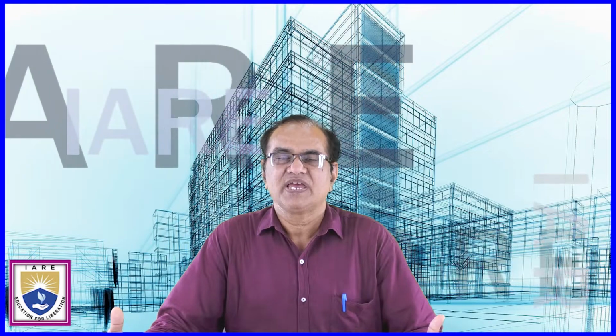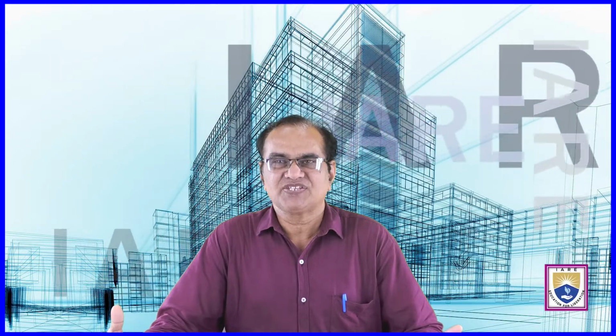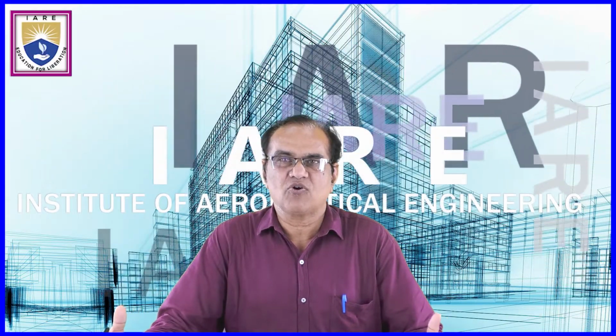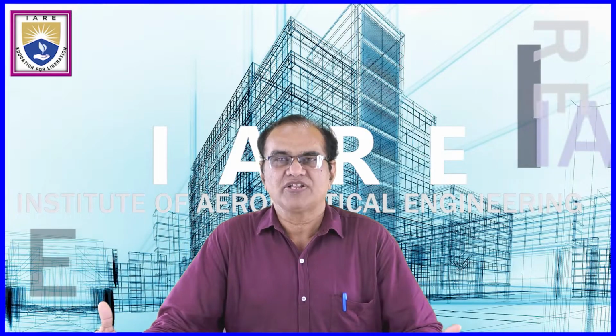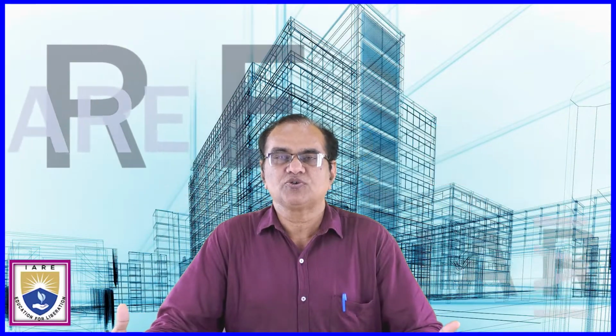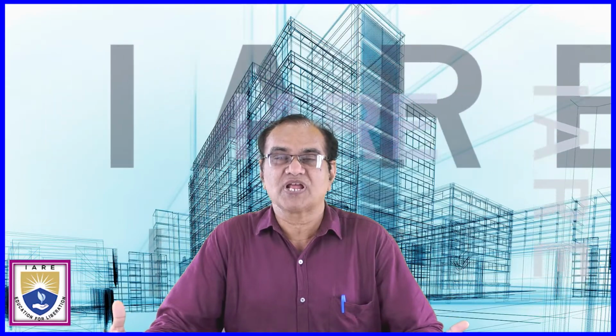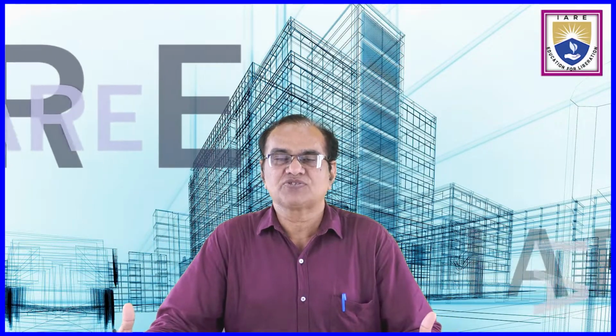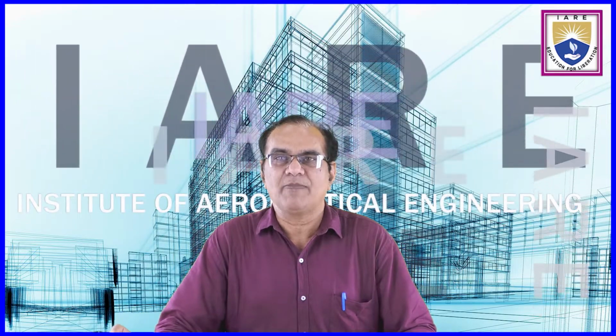The third one is the empennage system. Empennage system consists of horizontal stabilizer, vertical stabilizer, and the tail cone. The horizontal stabilizer is used to stabilize longitudinal motion of the aircraft. It also consists of the elevator, which is used to make the nose move up or down.